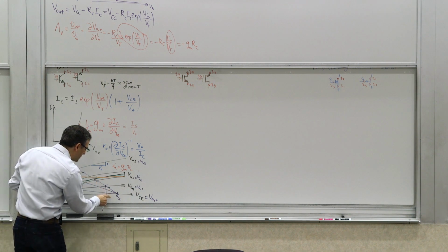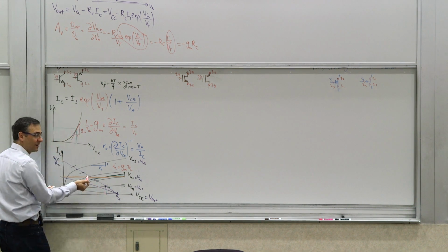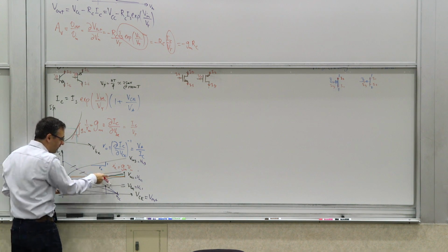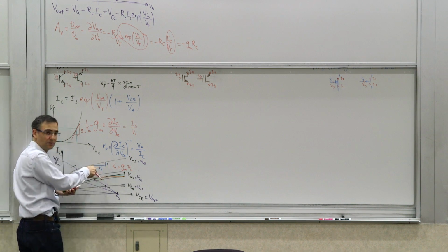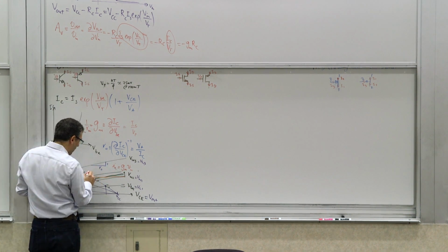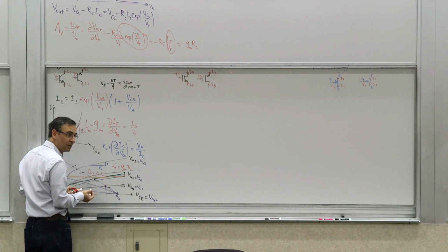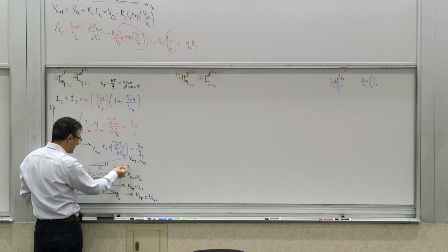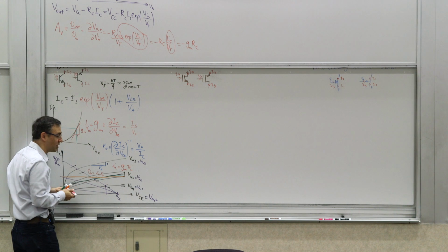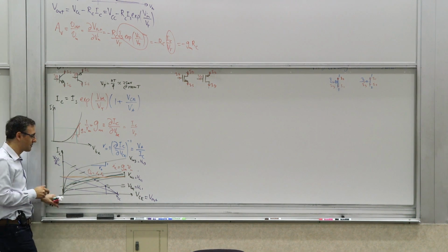And then that fluctuation needs to be converted to fluctuations in Vout. What is the conversion factor? It's RO, right? Because you're moving up and down in this picture and you are trying to convert it to left and right, so it will be 1 over the slope of this thing, which would be RO. So Vo would be IC RO for this flat line. And therefore the gain, Vo over vn, is going to be GM RO. So that's also consistent with this.